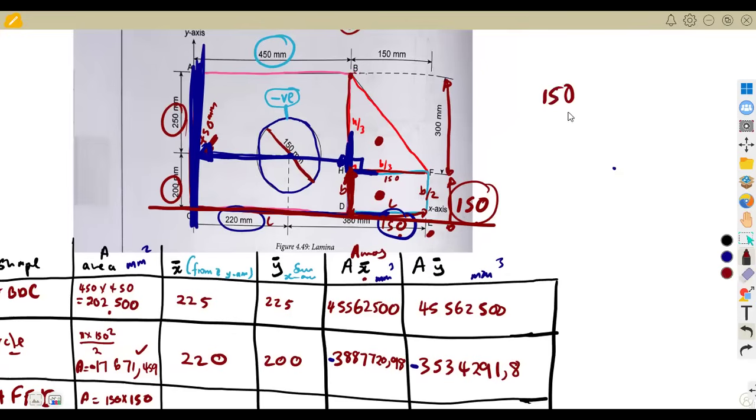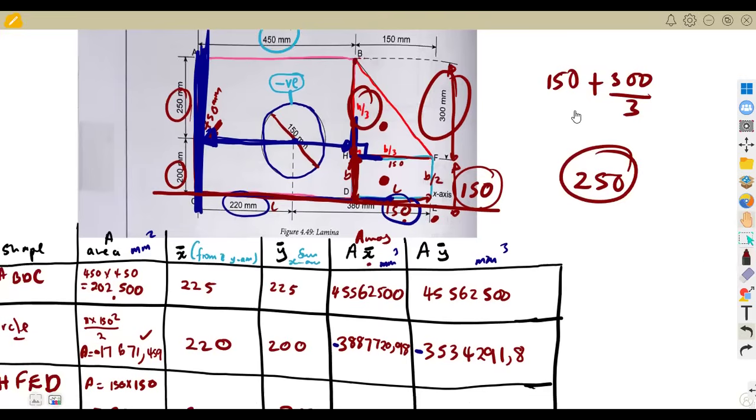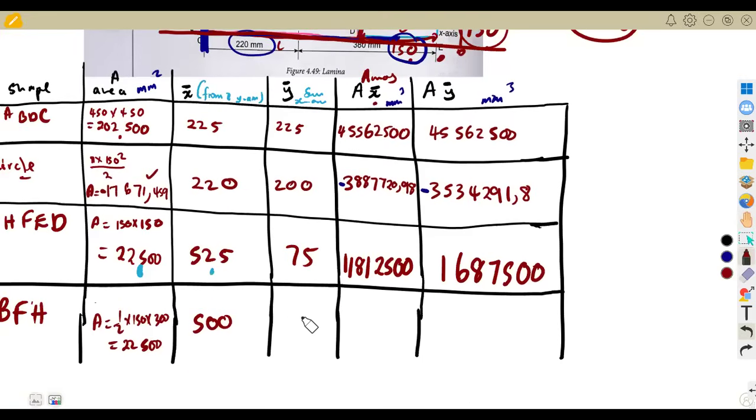We are going to cover 150 first. Then we consider from the perpendicular going up, this one is h over 3, so it's 300 over 3. So consider this. Go back and revise each and every part that you're given on our Centroids, guys. Revise each and every part. But also now you have to make adjustments on the questions. It's not like every question you're just going to use h over 3, b over 3. No, there are adjustments to be made.